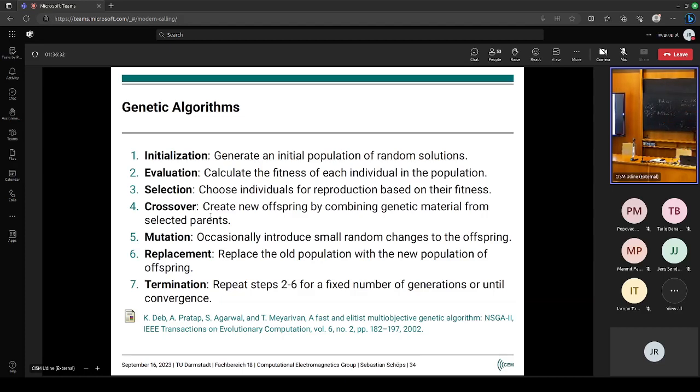One more thing that is nice about these genetic algorithms. What we sometimes see, especially in the finite element world, is that you change geometry, and at some point you may have missed a constraint. That means in the end, if you do it traditionally, not with splines, a mesher has to mesh the problem, yes? And the mesher may just not succeed because you have some intersection of some surfaces or whatsoever. So in practice, you will miss a constraint. I mean, that's my claim. You always miss a constraint. You always miss that some parameter may overlap another one, because those dependencies may be complex and nonlinear. You may not be able to understand all these interdependencies, and then your mesher will fail, or the simulation will fail, or the matrix of your problem will be so badly conditioned that it just doesn't go through.